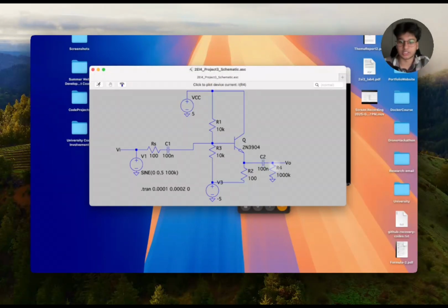Additionally, this resistance isn't part of the actual circuit, but I'm adding it here just to reference it to ground, so that when I'm measuring, it centers it to ground instead of having a voltage offset, which it normally does.